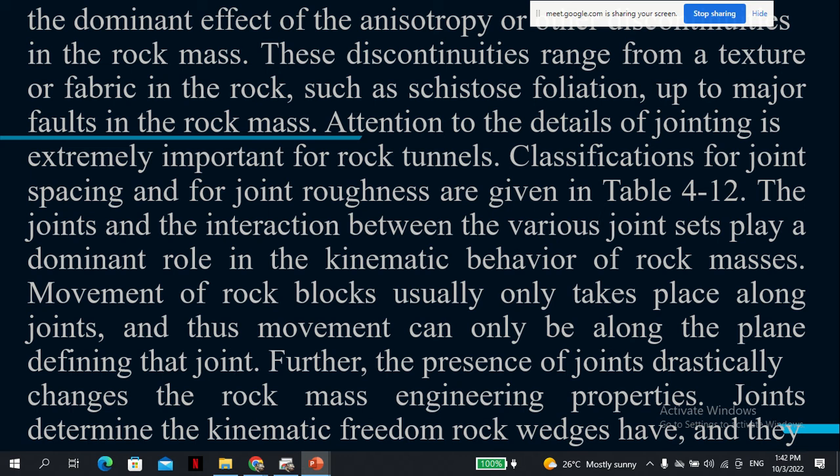So this is how you give it marks. If you know the strength is between 0 and 2, then in terms of the marks that contribute to strength, you give it low marks. If there is presence of water, if there's a presence of a joint, how continuous or how discontinuous the joint is, all these things will give it marks.